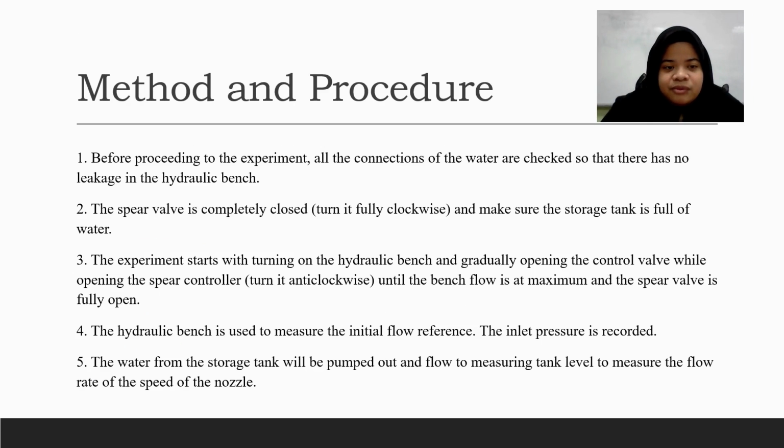We move to the next, which is method and procedure. Firstly, before proceeding to the experiment, all the connections of the water are checked so there is no leakage in the hydraulic bench. The spray valve is completely closed. Turn it fully clockwise and make sure the storage tank is full of water.